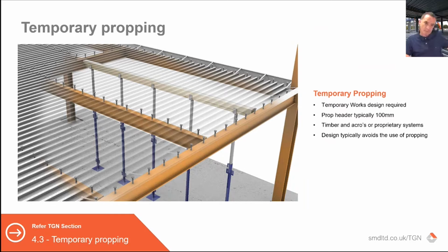This is just an image, more than anything, from a temporary prop point of view. Temporary props will be indicated on our drawings. There is a temporary works design required, proper head, typically 100 millimeters, and there are numerous proprietary systems that we would typically use because of the loads involved on long spanning decks. But I would say 95, if not more, percent of what we install will be avoiding the need for temporary propping.